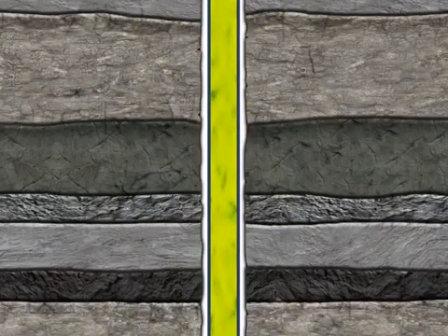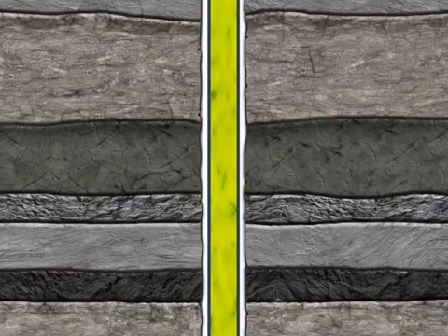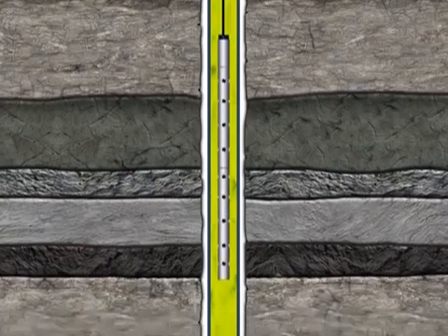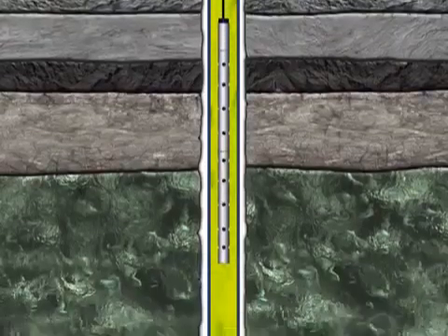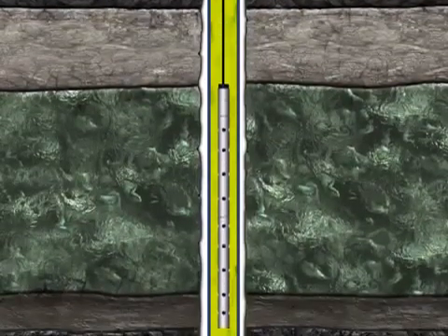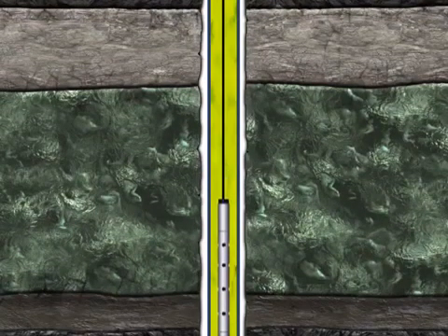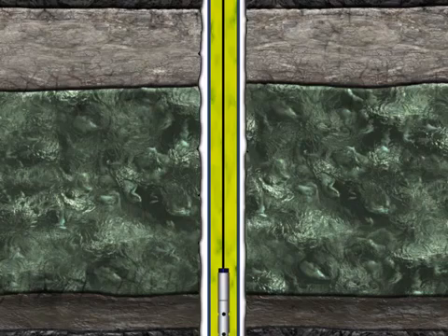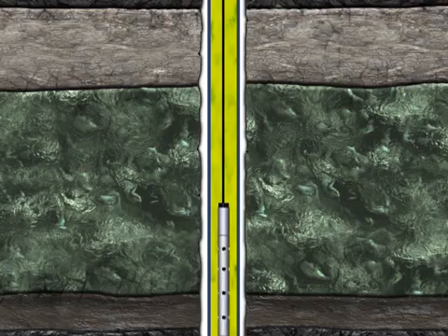To establish a path with the hydrocarbons stored in the pay zone, a perforating gun is now lowered to the target depth. Wireline is the preferred conveyance method for short and light gun strings. To deploy long and heavy gun strings, a technique referred to as tubing conveyed perforating, or TCP, is required. Using sensors that are part of the gun string, the guns can be accurately positioned in front of the targeted reservoir.